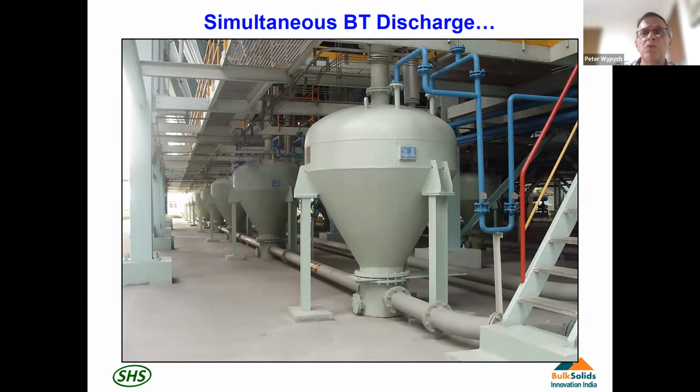This is one system I would not recommend, where they just have these tanks at the bottom. These are bottom discharge blow tanks, and there's no aeration there. It's asking for trouble. So when you fill up your blow tanks, there's no pre-pressurization on these. Ash goes in, it runs out in the line. If you've got a good ash, yeah, you'll get rid of it. But if you've got a coarse ash or a bad ash, it'll all block up, no worries.